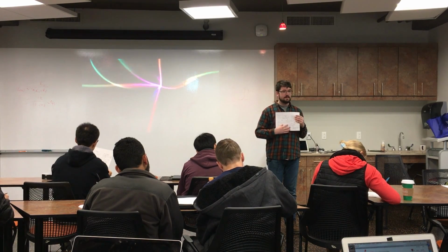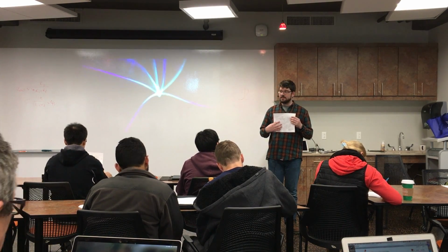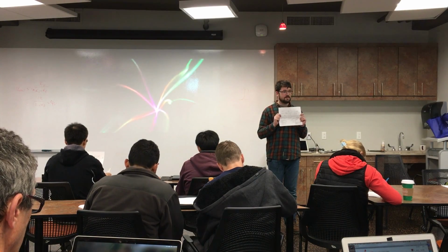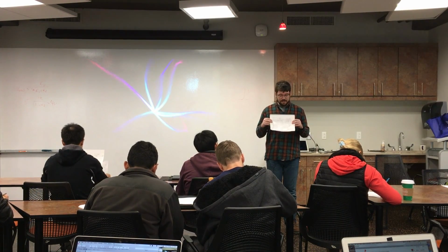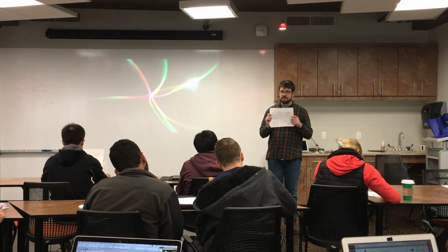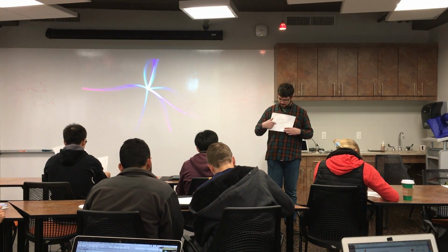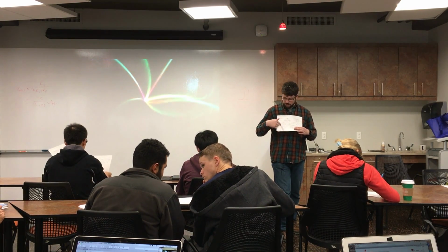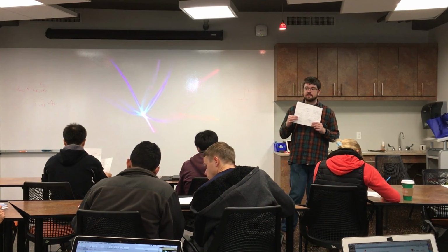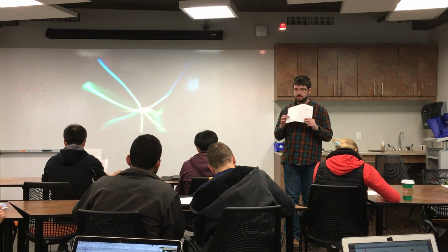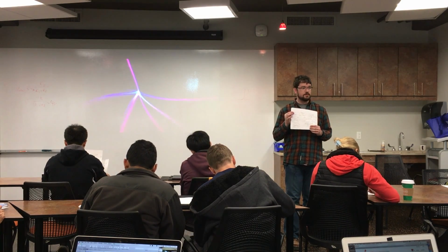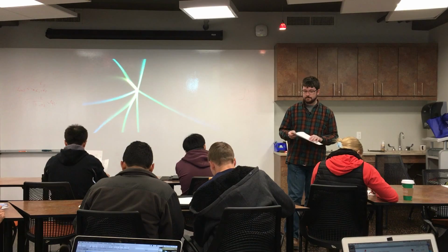Okay, so does that make sense, how we process the LVDT signal or DC-DC signal with a circuit like this? It looks pretty simple, but it's not necessarily once you start getting into the fine details. Down here in this corner, we just have decoupling capacitors on the power rails, which help filter the voltage to make it a nice clean signal.